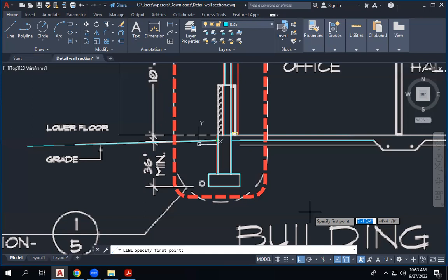It can be done with soil or with quarry dust. Any materials can be used, depending. If the load bearing capacity of the soil is not that high, then they will put quarry dust and do the compaction. So we will have a layer here, the filling layer, and on top of it we will have the concrete slab. That's the slab that we are all used to. That slab should be finished with the foundation point where it should be here.